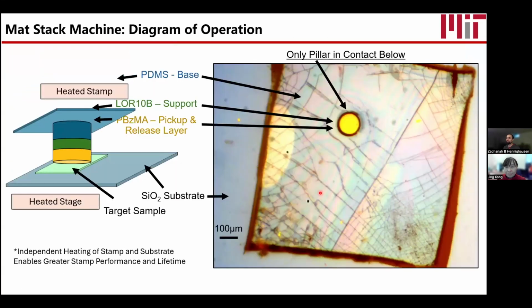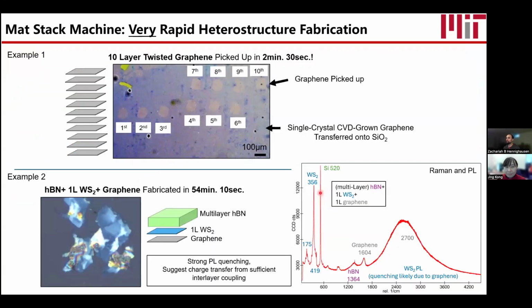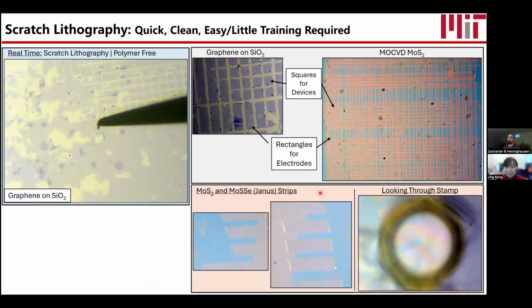And so you can even see some issues with, let's see. So for example, you see how the graphene's all broken up? That's because this transfer process, which we've improved upon, didn't work that well. So the graphene picks up from the surface, but it didn't transfer that well because the SiO2 didn't want the graphene. So that's the trick that needs to be figured out.